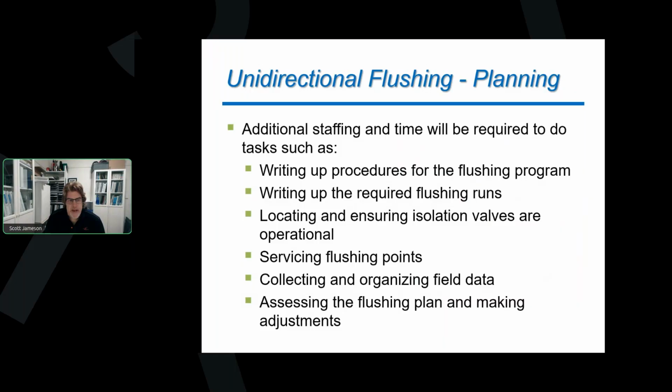So some of the tasks where you might need some additional staffing, or for a lot of you, whoever's writing the program will be doing this also. You're going to have to write up a procedure for doing this flushing program. That's going to include where am I flushing from, what valves am I closing, how is this going to work for us.